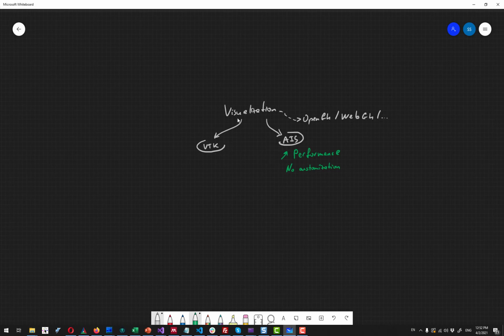Then I would say that it's really tailored to CAD. It means that it does a pretty cool job whenever it comes to visualizing CAD geometries, like all these BREP geometries, as TopoDS shapes, and also assemblies, which are the hierarchies of BREP shapes. And basically, since it's tailored to CAD, you can take advantage of pre-implemented visualization modes such as wireframe and shading, and also what we haven't touched today is hidden line removal mode, for example, all these things. And also it offers a pretty darn fast selection mechanism.